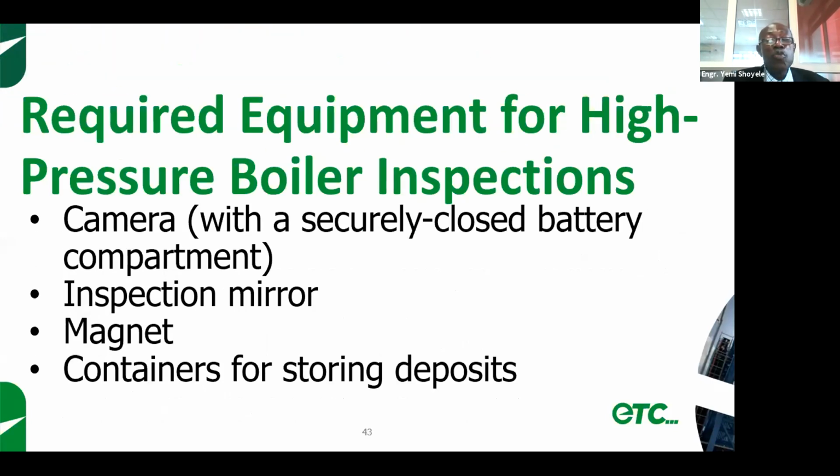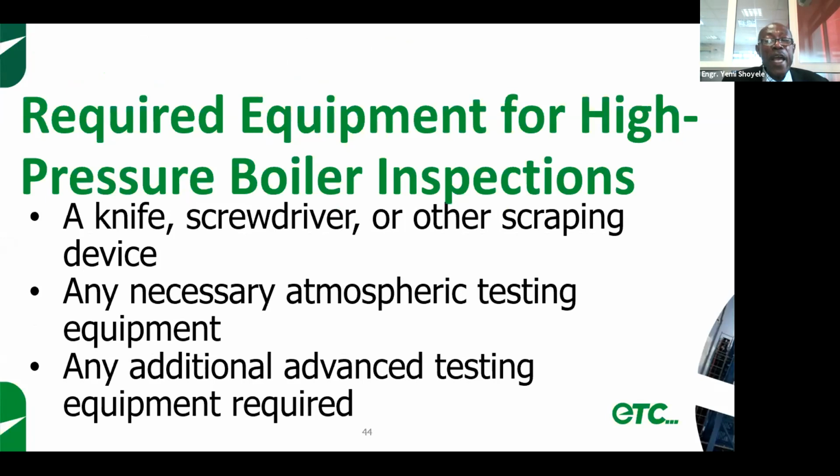with a securely closed battery compartment. In fact, you have to use what we call intrinsic cameras, so cameras that cannot cause sparks or anything. Inspection mirror, magnet, and a little container which you sling over your shoulder for storing deposits. So when you have some deposits in the boiler, be it scales or soot, you have to evacuate them. A knife, a screwdriver, or other scraping device.